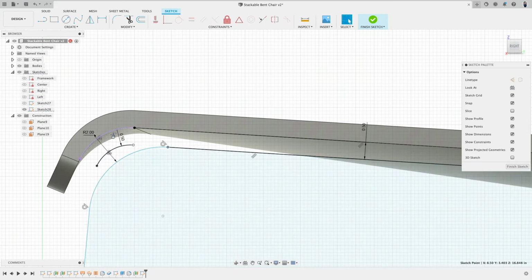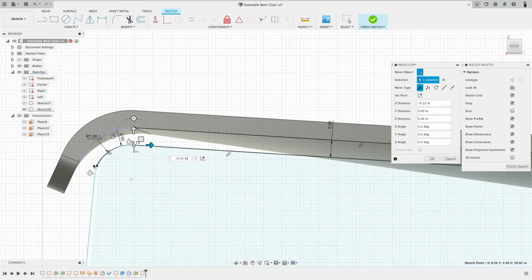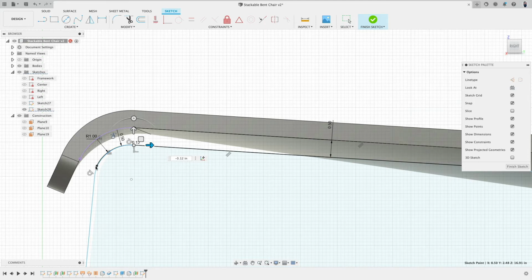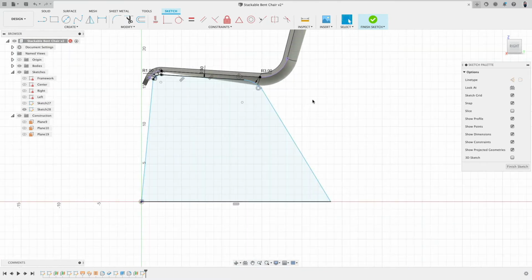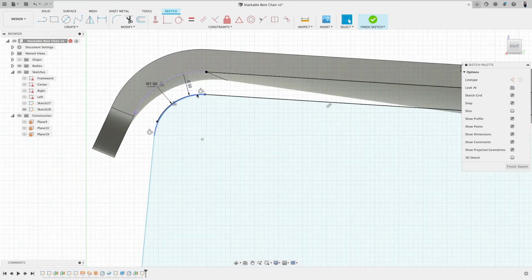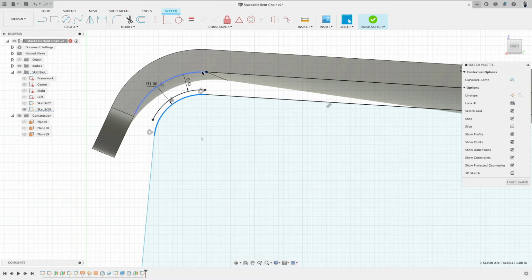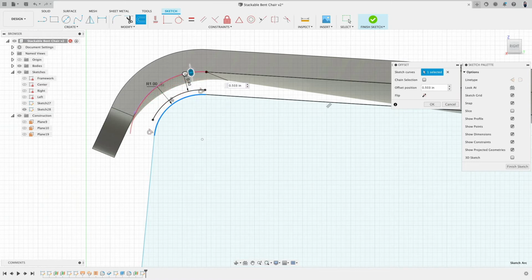we can actually, when we drag this over, get an idea of maybe how big or small this radius could be. You see how when I overlap this, I'm eyeballing this. Very good. We don't want this to actually snap to it, so I get close, press M, and then only slide it. This way, not by accident, I glue maybe this point to this point. Okay, very good. So this way I made sure that this nicely is parallel, or not parallel, it's a curve, but essentially this arc has the same shape as this one. In case it would grow bigger, it would be matching it. No, there you see it.